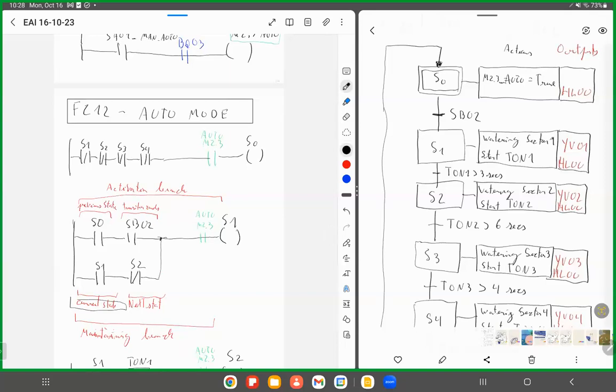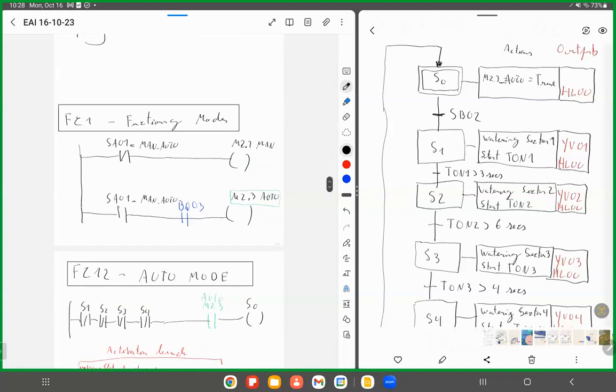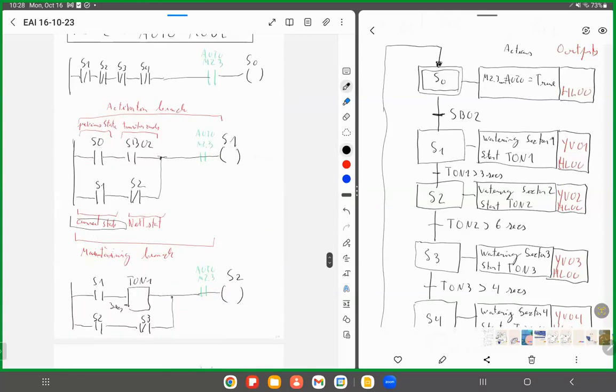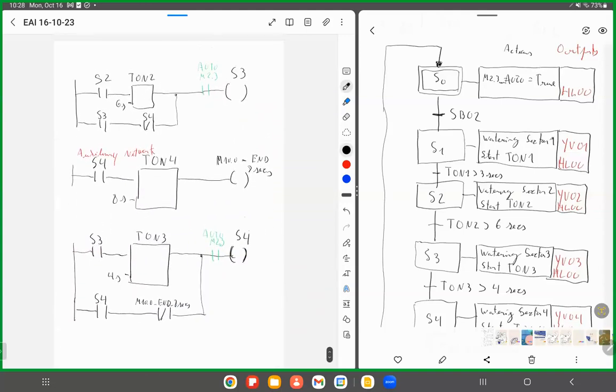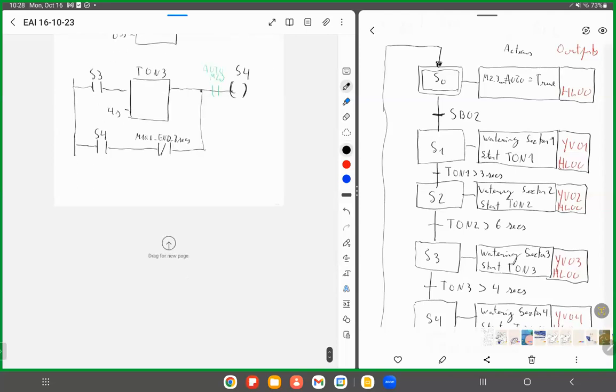If in the middle of this, your water falls below, it will still operate, but that's for 10 milliseconds. In the next loop, it will go here, and it will decide, oh, I cannot be in auto mode because I don't have enough water. So your response time is 10 milliseconds, but that's very short. Okay. What else? That means, don't forget, now in manual mode, what we must do is something like this.